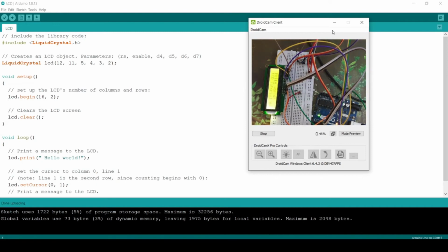Okay, so my LCD has been powered here, so you can see here. Okay, so this is my potentiometer. So here I have shown it with the tester, this is my potentiometer here. Now what I am doing is varying the potentiometer, and you can see here, I am not getting any words here. You can see I am getting a blank screen, a completely yellow screen.